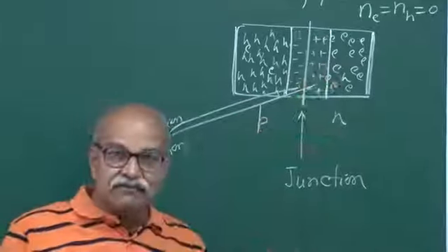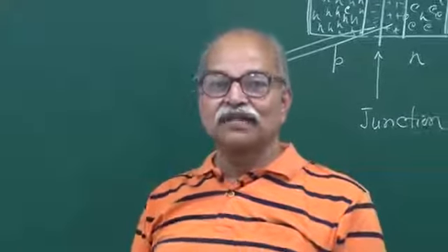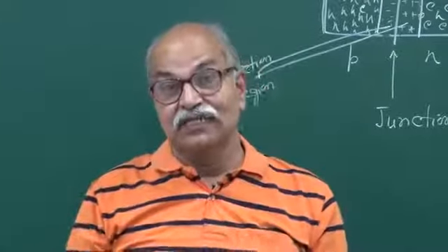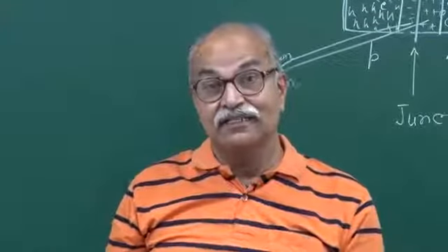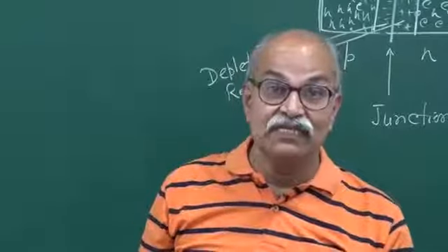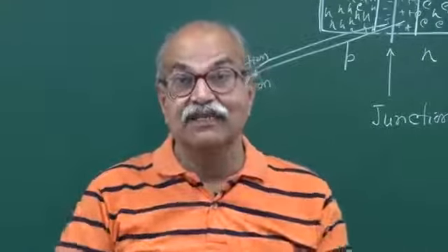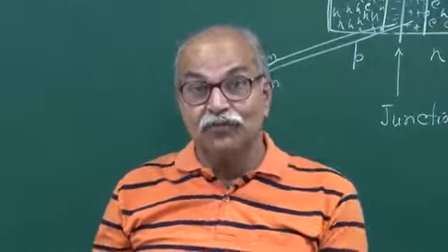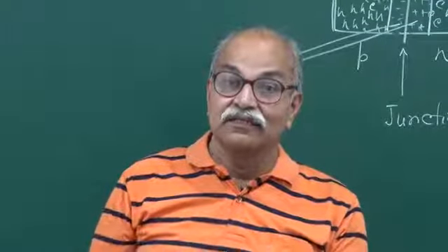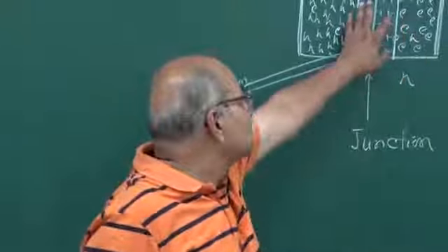But then at any temperature, we told earlier, new electron hole pairs are created, because in that material you have a thermal distribution. These electrons can get energy from the crystal of the order of the Boltzmann constant k times T. So because of that thermal distribution, energies are taken up, energies are given away. So new electron hole pairs are always created, and the old electron hole pairs are destroyed in a normal semiconductor. That process is still here in this depletion region also.